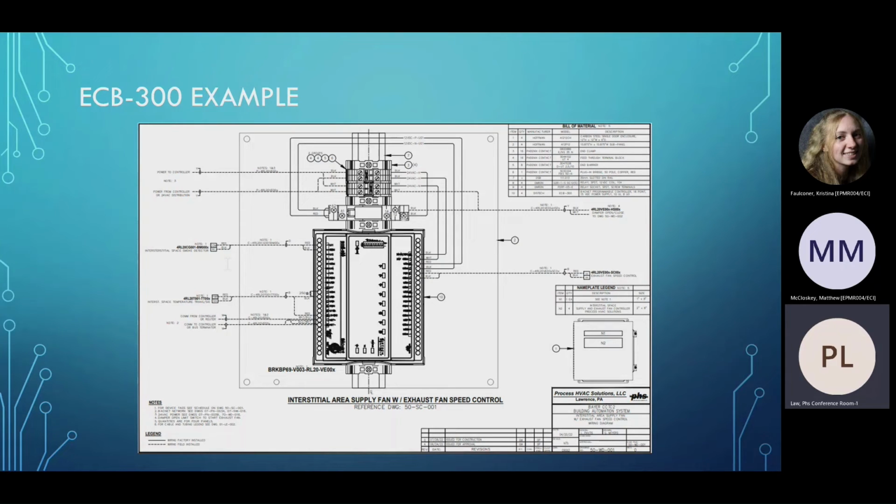There's also a smoke detector associated with each one of these that will shut down everything if tripped. So it's kind of like a fuse. And then here's our communication lines coming in here. And then we have the SC fan coming out. That's the speed command, works the same as the IDF room. And up here is a relay that we send a 12-volt signal to the 12-volt coil.